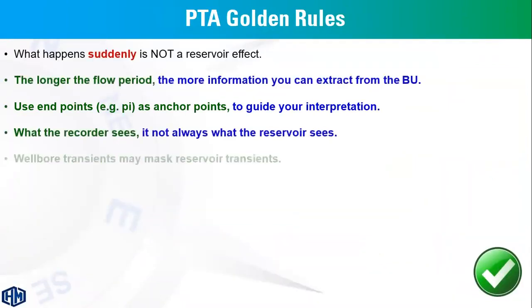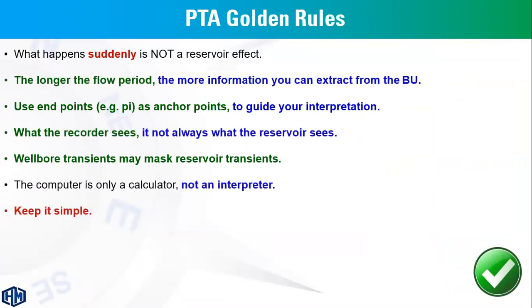Finally, in this webinar, I'd like to highlight some important rules in well testing. Any sudden effect in well testing is not related to the reservoir. The longer the flow period, the more information or data we have about the reservoir. In well testing interpretation, you have to match the end points, or anchor points, the start and end of every drawdown and build-up interval.